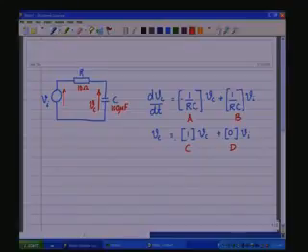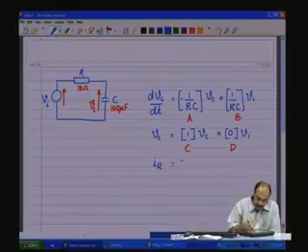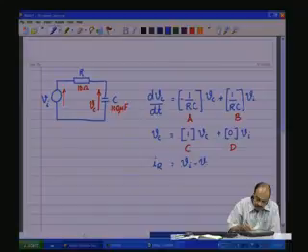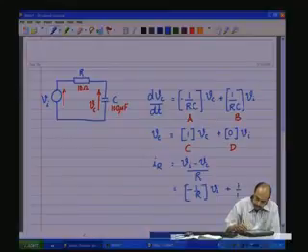Let us say you want to have output here as IR instead of the voltage across the capacitance. IR would be the current through the resistance, which is same as the current through the capacitance, which is nothing but VI minus VC by R. So, this is nothing but minus 1 by R into VC plus 1 by R into VI.